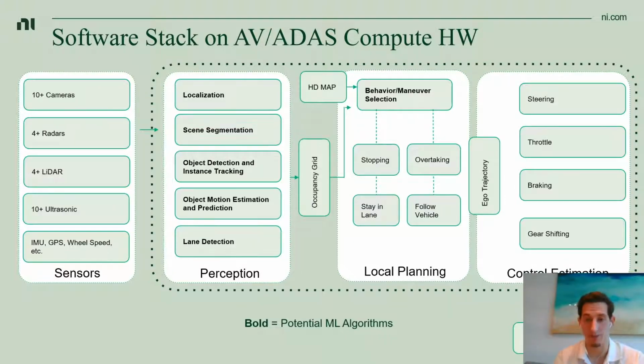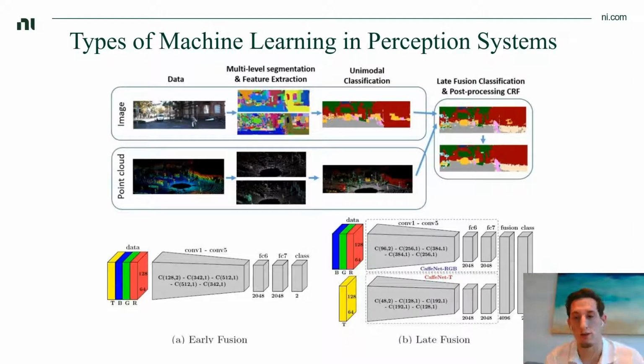What's also interesting to note is that if you take a look into some of those perception algorithms, those algorithms in the perceive bucket there, they could have any number of different permutations. They could have early fusion, which is a concept where you receive both camera and LiDAR information and cascade that information together, send it through the algorithms, namely the convolutions that simplify and the deep networks that actually do the detection, and then you get a certain output. Likewise, you could send it through a different algorithm that takes camera and LiDAR separately and sends them both through their own convolutions, their own series of algorithms, and then compares the output of them.